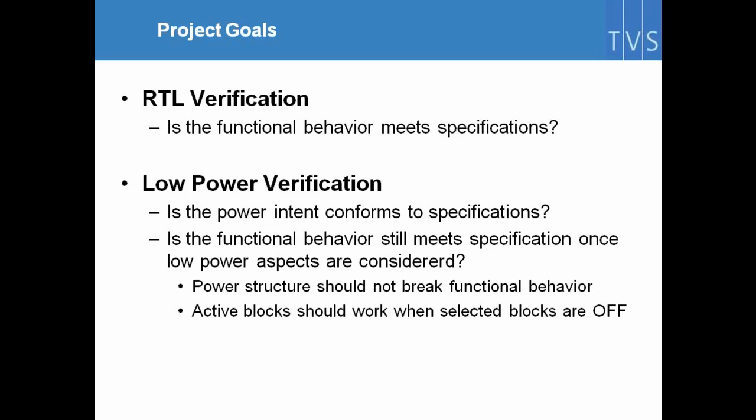So our goals were first to verify the RTL. The RTL has some features, and we need to verify the functional correctness of the design. But most of the work has been spent on the low power verification. We needed to verify that we conform to the power specification. We also needed to verify that in the different power modes, the design was still behaving properly. It's not because you switch off one block that the rest of the design cannot work. The rest of the design should work.